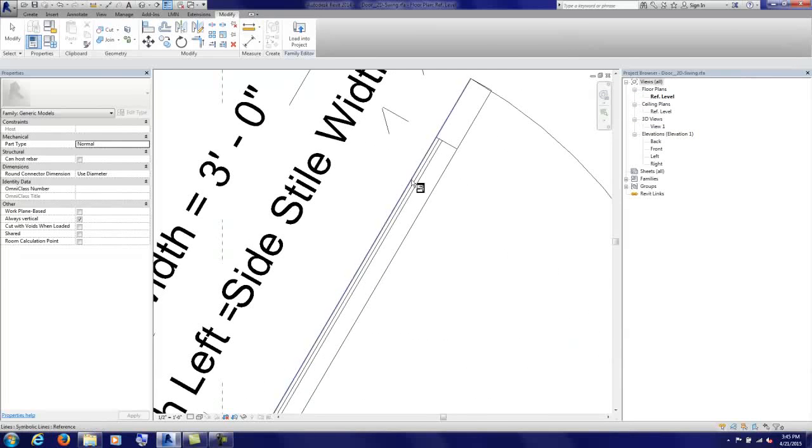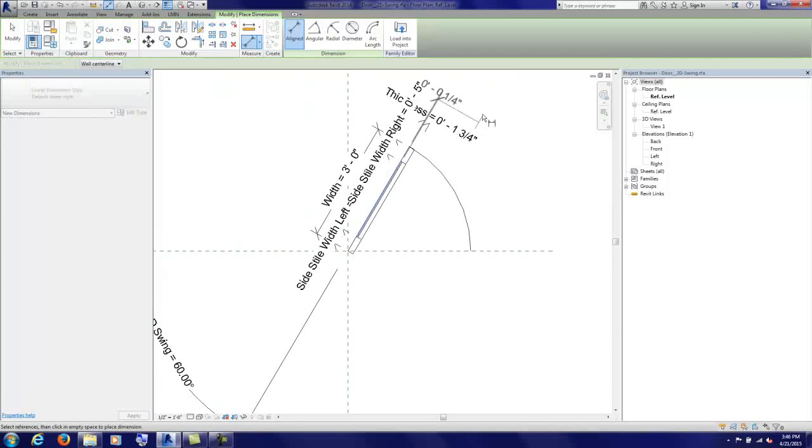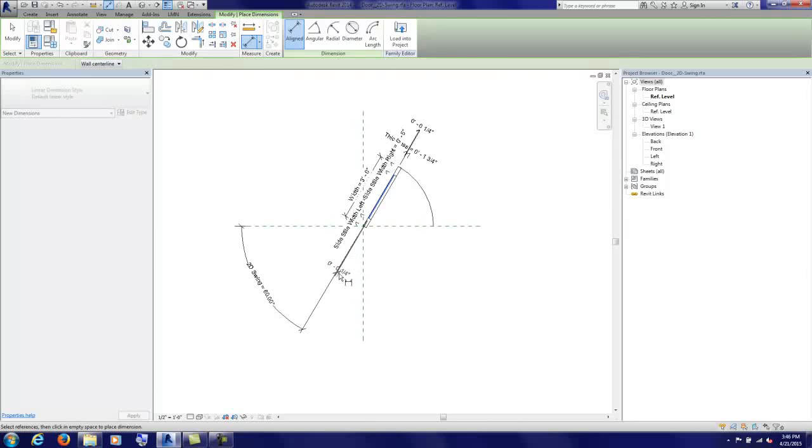Alright, what we do need to do is add dimensions so that we can get the glass to appear like it would if it's centered within the door. And sometimes it's a 1/4 inch piece of glass, and sometimes it's going to be a 1 inch piece of glass. So I'm going to strike a dimension, and this is going to be important that we come from tabbing over until it says reference lines, reference lines, reference. And I'm going to go to the first offset. Then I'm going to go from that offset line to the next one. I'm just going to pull a dimension off.